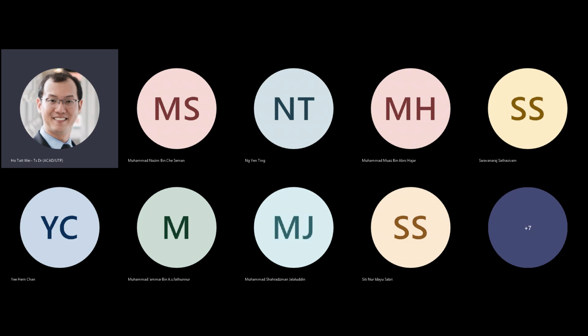And so the way we would learn how to assemble logic gates, the NOT gate being the simplest, is we think about them as a pair of complementary switches. When one is closed, one is open. So let's go ahead and see how we would derive the complementary switch network for this NAND gate.